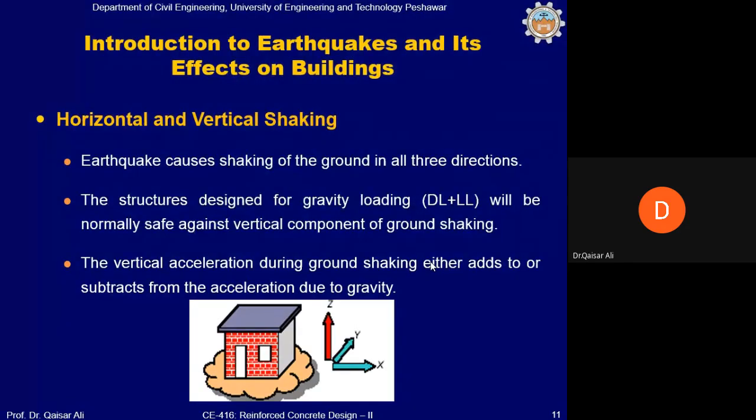And when the direction of the acceleration is downward at a particular instant of time, then the mass multiplied by the acceleration will create an inertia force in the downward direction, and this force will be added to the weight of the structure. This will aid the weight of the structure, and the weight of the structure at a particular instant of time will be increased. These things must be taken into account while designing